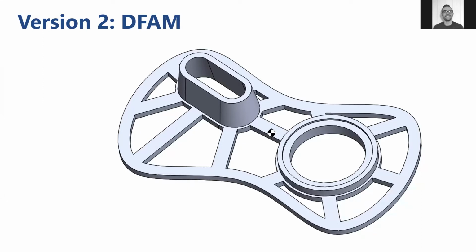So of course we've retained the same mounting point, but now we're looking at having a wider base, so there's more area to hold. Of course, we've removed all the superfluous material and just left this shelled out. And we've removed the cap layers, both on the cap of the handle as well as the top of the fixture. That way we're not printing support all the way up into the handle and into the bottom of this part. So we're saving even more material consumption there.